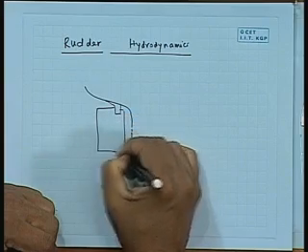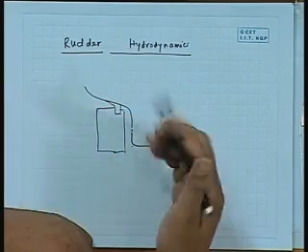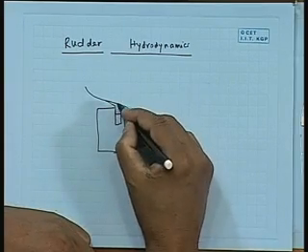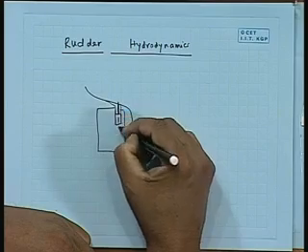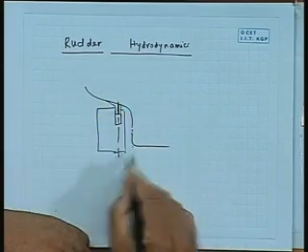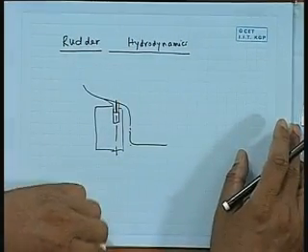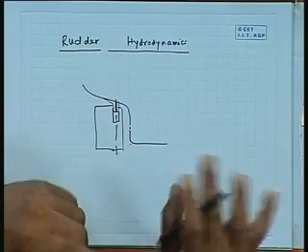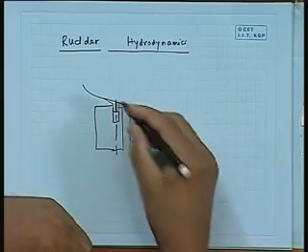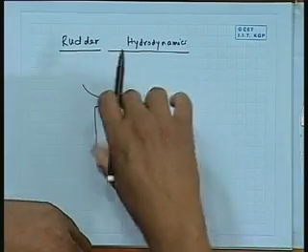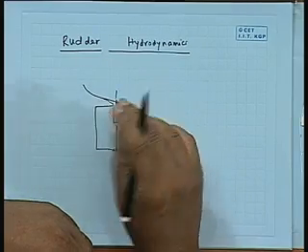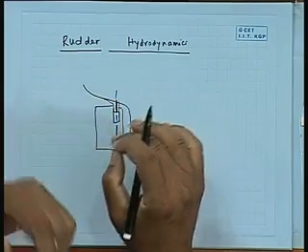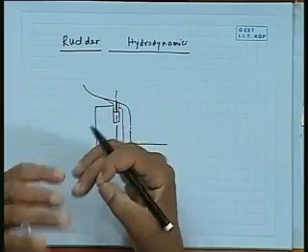I do not want to go into the detail. There are rudders which are balanced, not balanced, having a post. Number of types of rudders are there. Essentially rudder is a device which you can rotate about some axis, and by rotation it causes primarily force in the y direction. This is what you are interested in. You want to generate turning moment and turning force. This is what exactly it is.